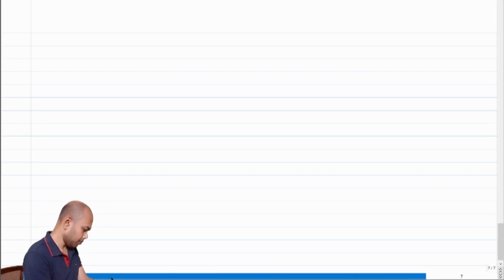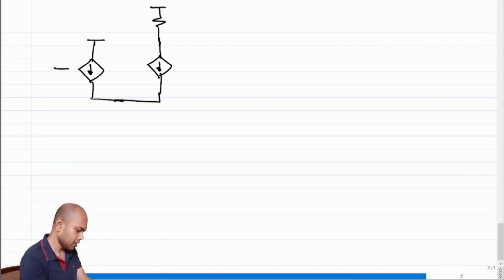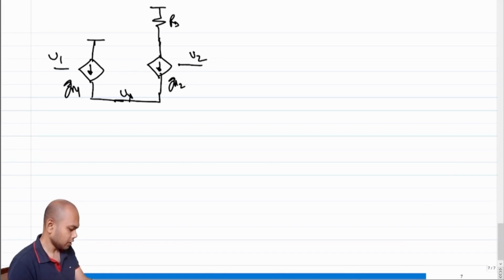Okay, so now it's time to see what a real transistor differential amplifier would look like. Till now we have been dealing with this structure, right? And this current was going into some resistance, and let's say for the purpose of this discussion, I keep the drain resistance as some arbitrary resistance RD, right? And let's say this is V1, this is V2, this is Vx. So this is the small signal equivalent of the structure that we want.